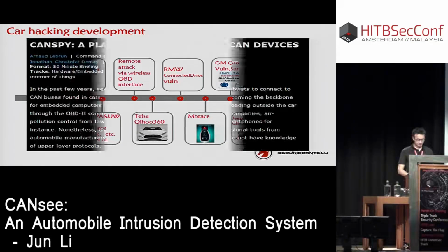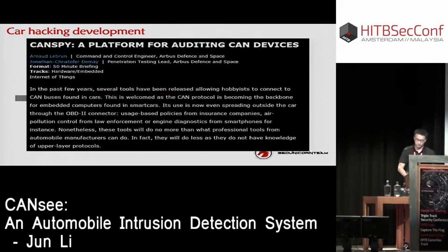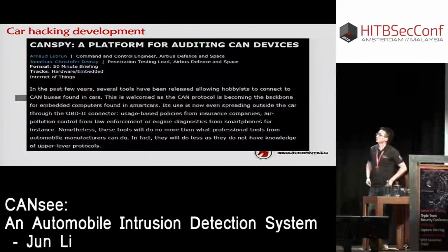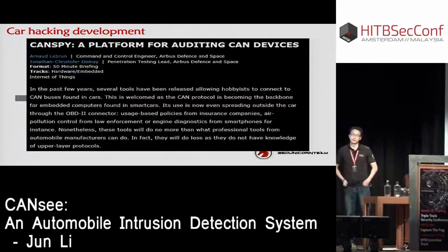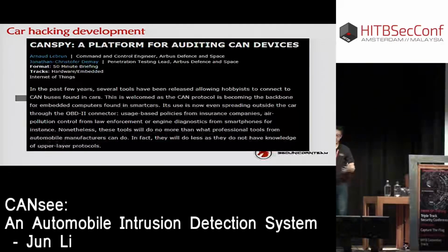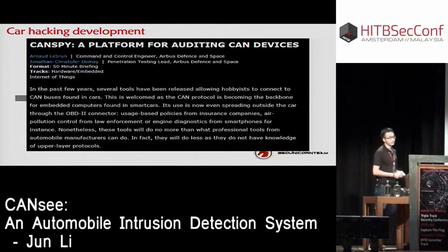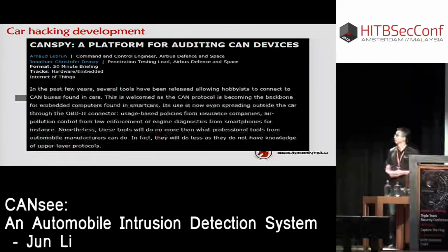So in order to control the physical features of the cars, you inject CAN packets. CAN is a network protocol used to network the different ECUs. What is an ECU? I will talk about that later. The ECUs are connected, and the connections are often not encrypted or authenticated.